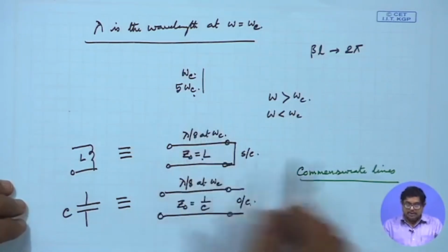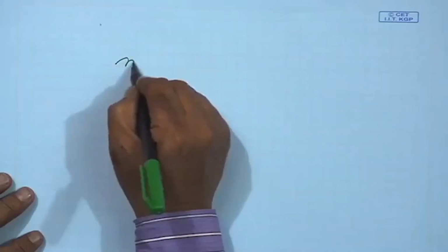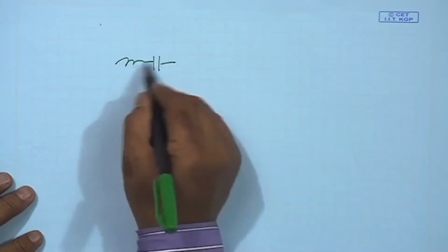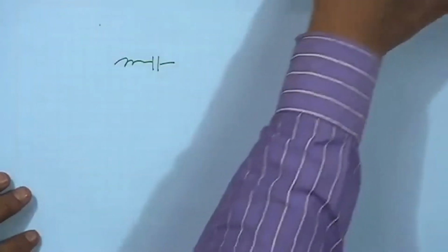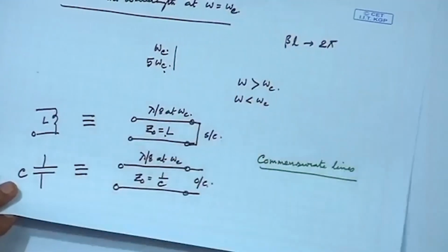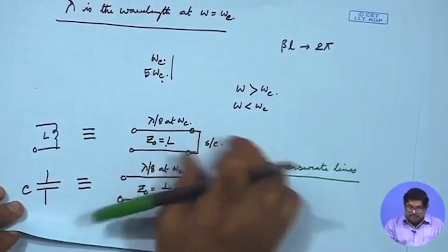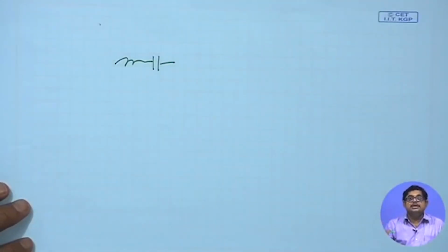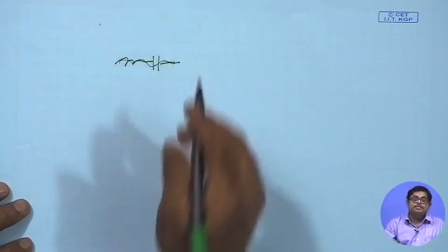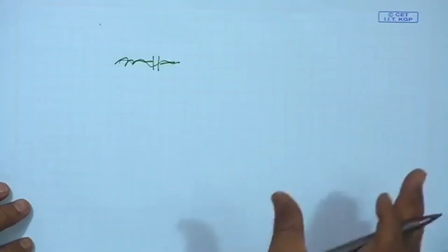So, this is Kuroda's identity, but one more thing is that in high frequency another problem comes: these lumped elements, suppose I have one L in a filter, then a C. Now, their distances also matter, because there is phase difference between them. When you are putting them, those distances may not be feasible, and sometimes I need to put some more gap or some less gap. So, some redundant line needs to be incorporated, so that these gaps become feasible, and there are sizable gaps between them; some match sections need to be put.